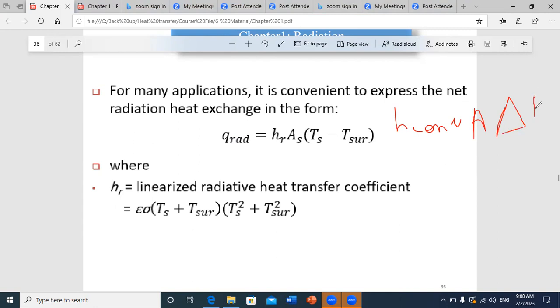It's true that radiation flux is not linear because it's proportional to T to the power 4, but in modeling, dealing with a fourth-order term is really complex. If you are writing a model and want to solve for heat processes, linearizing the radiation term helps a lot in numerical calculation.